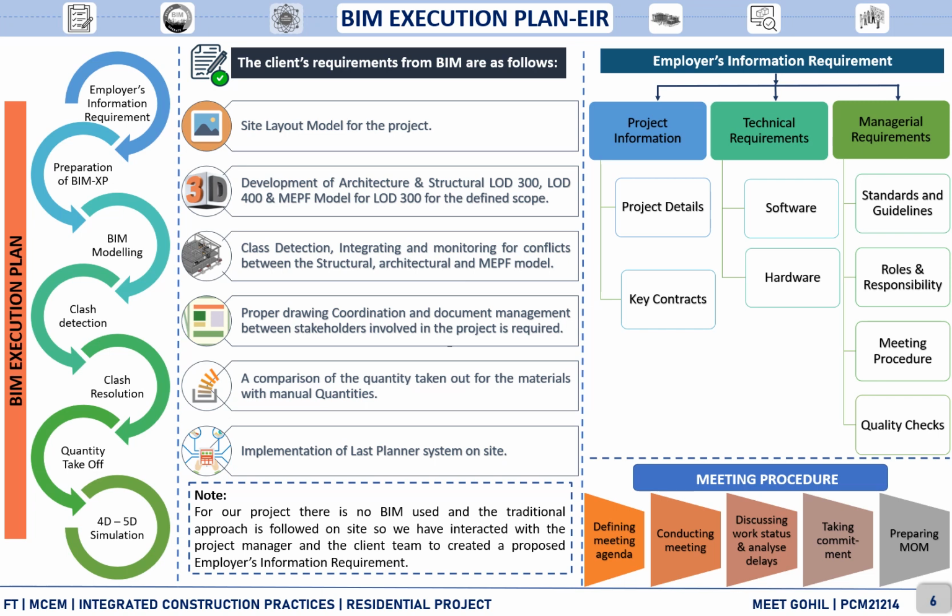So we have interacted with the project manager and the client's team to create a proposed employer's information requirement for our project. The client's requirements from BIM are as follows: site layout model for the project, development of architectural and structural level of detail 300 and 400 models, and mechanical, electrical, plumbing and firefighting models for level of detail 300 for the defined scope of work.